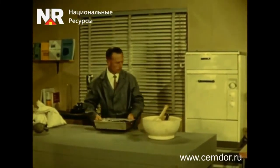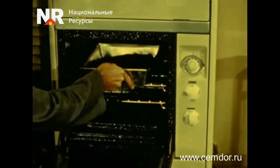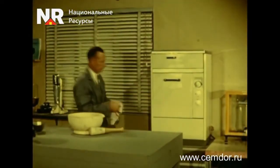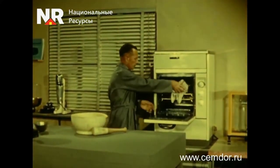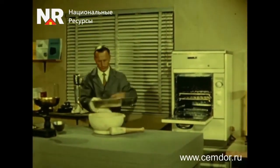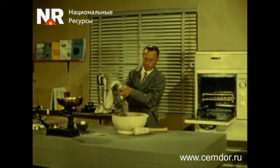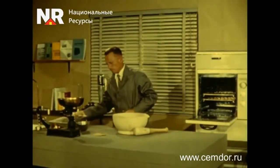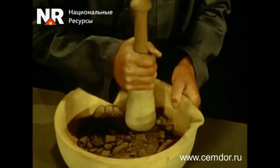For this, the soil sample prepared for testing is dried in a drying oven to an air-dry state. After drying the sample at a temperature not exceeding 100 degrees Celsius, the soil aggregates are crushed.